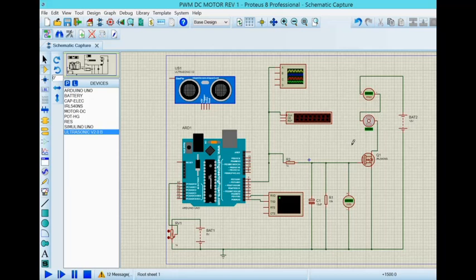So to maintain a level, you definitely want to have a flow of water going into it. That will be the idea: to have this measure the level, perhaps use this to have the proper set point that I want, and to use pulse width modulation to control the inlet water flow.